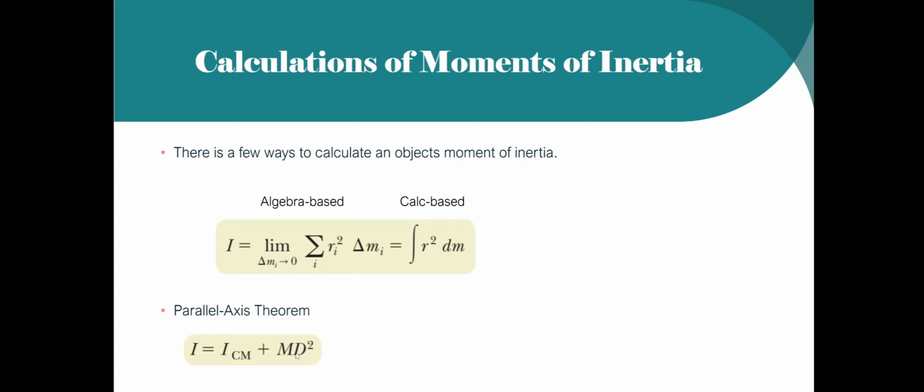So we're adding mr squared just from here. Okay, we're adding in an extra mr squared, and that'll give us a new moment of inertia. It's a little bit hard to do here in the video. I'll do it on the whiteboard for you. I'll show some pictures and drawing that out and how the parallel axis theorem works. It's a nice, quick and easy little way rather than doing an integration or something like that.